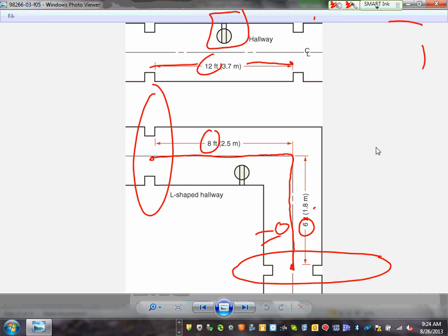You know, it's a good idea to throw in a receptacle. But what's the minimum? When we design it, you're going to design it, guys, first based on the minimum, then you're also going to go with common sense. So if you added a receptacle here and you gave it to me, I'll say a good idea. If you added 2 more receptacles here, you might have to question that one. So you're going to use your judgment.